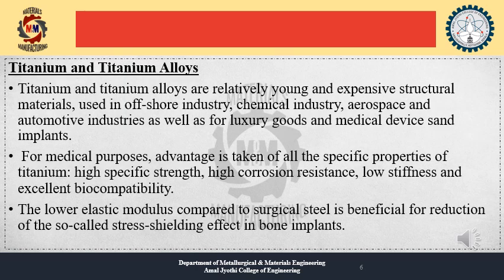In this slide, we are discussing titanium and titanium alloys. Titanium and titanium alloys are relatively inexpensive structural materials used in offshore industry, chemical industry, aerospace, and automotive industry as well as for luxury goods and medical devices and implants. For medical purposes, advantage is taken of the specific properties of titanium: high specific strength, high corrosion resistance, low stiffness, and excellent biocompatibility.